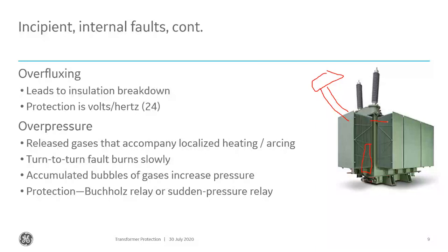Okay, so some of the most important elements that we really have are the restricted ground fault, transformer differential, and the instantaneous and timed phase and ground overcurrent. Now, what we employ will depend largely on the type of transformer we're using.